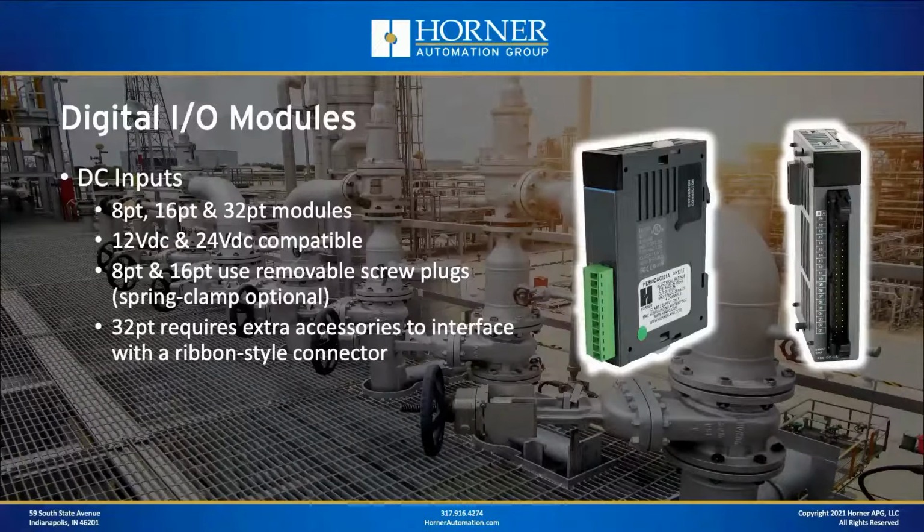Those are available in 8, 16, and 32 point versions. They're compatible with both 12 volt and 24 volt signals. The 8 and 16-point modules use removable plugs like we've talked about before, with the optional spring clamp plugs recommended for those who are looking for fast wiring or for the ability to wire any particular conductor from the front without disconnecting. Now there's also a 32-point card.